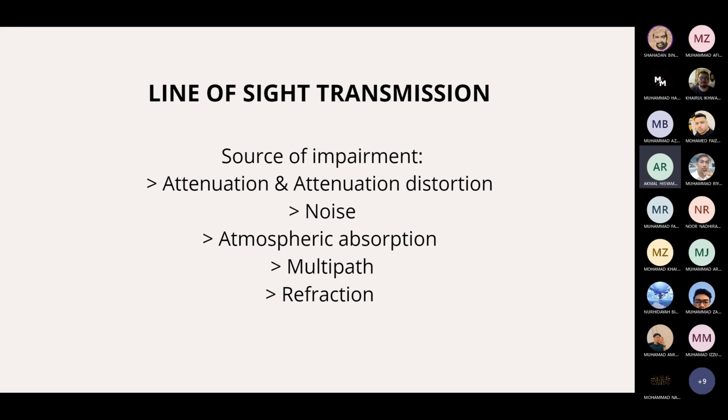In water vapor, the peak attenuation is near 22 gigahertz and low attenuation is below 15 gigahertz. For oxygen, absorption peak near 60 gigahertz and lower below 30 gigahertz. So meaning lower frequency band usage helps to reduce atmospheric absorption.